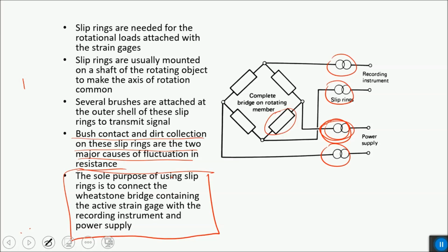So effectively, once we have covered all the types of sensors based on their working principles, not based on the measurement objective, we design the signal conditioning circuits for different types of sensors based on different working principles. For example, capacitive sensors, resistive sensors, very small changes in resistance, changes in voltage. We are actually completing that whole category of sensors, not just that parameter. So we don't care whether the resistance was changing because of the change in temperature or strain or change in light intensity. We are only interested in the change in resistance.